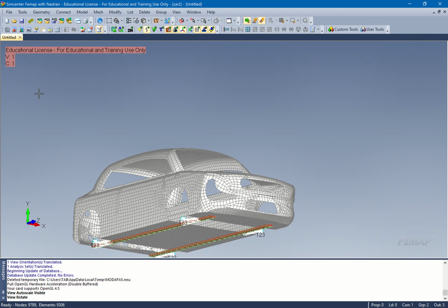The other part is, so if it's 0.051 seconds time, then in terms of the sine wave then would look like that, wouldn't it? We only do half a sine, but the sine would be like that, right? So the period of the sine wave, well, that going over the bump as input would be equal to 2 times the half sine. So the period is equal to 0.102 seconds. That would be the period, correct?